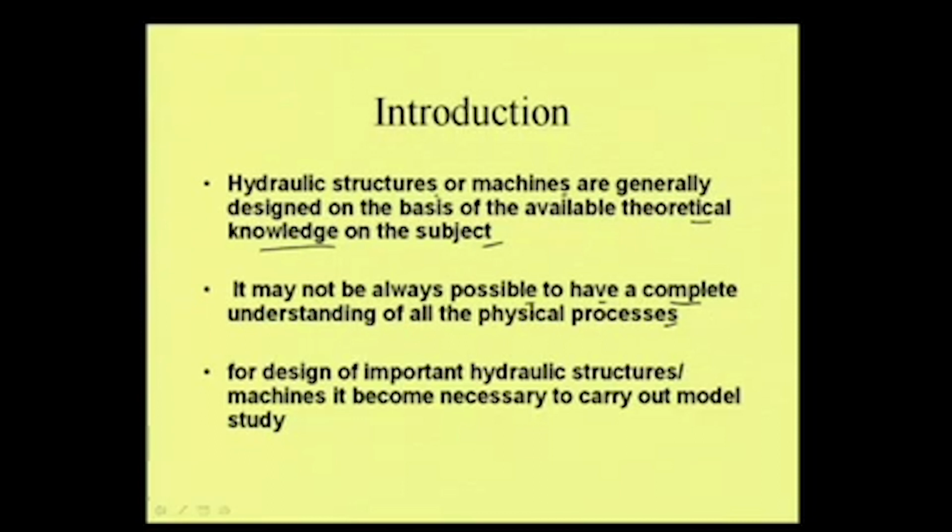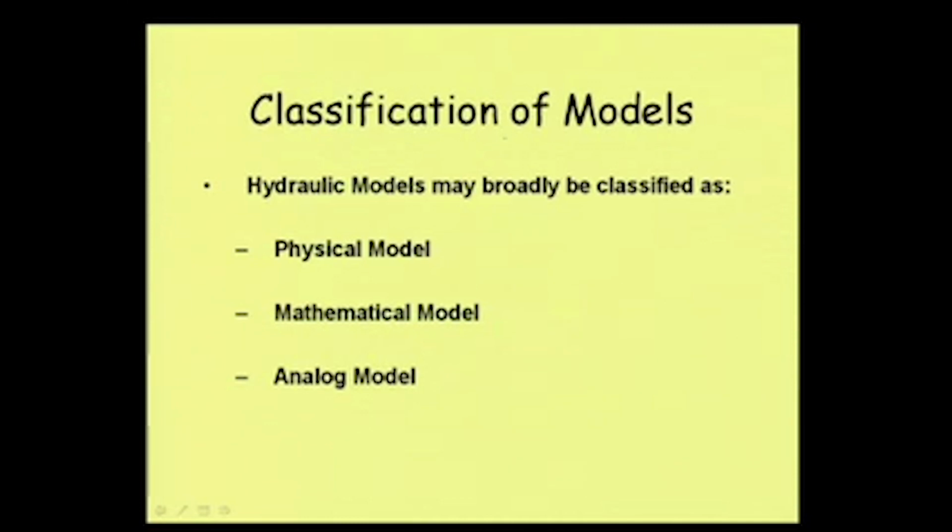If we apply only our theoretical knowledge and design, this design may not be successful. For the design of an important hydraulic structure, if the design fails and it has very important consequences, then for design of important hydraulic structures or machines, it becomes necessary to carry out model study. So there the question of conducting a model study comes. That means for those phenomena where we do not have a very clear analytical understanding, such as the scouring problem. We did discuss scouring earlier in canal design, but it is very difficult to have a clear-cut understanding or to develop a theoretical relationship for these things, and in those issues we need to go for model study to have a better understanding. Right. Then let us classify the models.